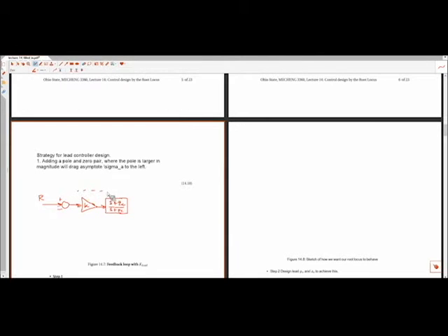And so before we said a simple proportional gain, here we are making a dynamic compensator or controller, G1. So this has dynamics associated with it. It's now going from input error to output, input to the plant. This has a differential equation associated with it, as opposed to just a static gain on the system. And we call this form a lead controller.